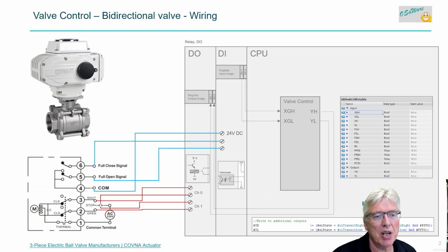And it's going to be a state machine, or should be a state machine. These control outputs could either be active when the valve is opening or closing, high or low. Or if you're using only one output, we have to keep one output steady high. If this valve was of the type where you have to keep it open or closed, then when you remove the control signals, it would shut or open depending upon whether it's fail to close or fail to open. So there's an option in the program here, a parameter, steady outputs.